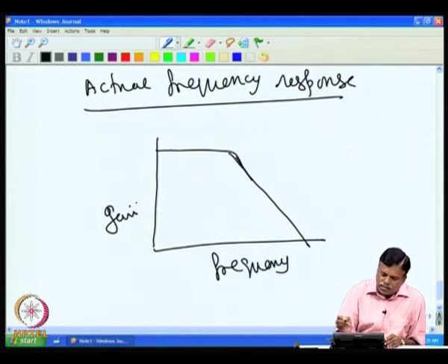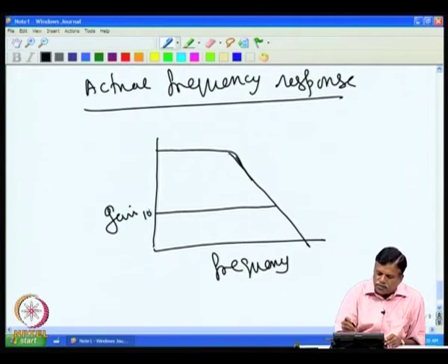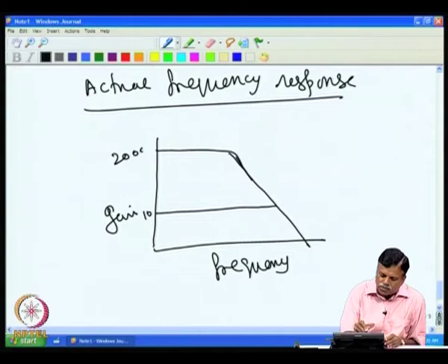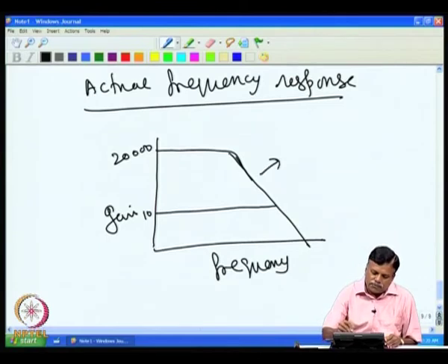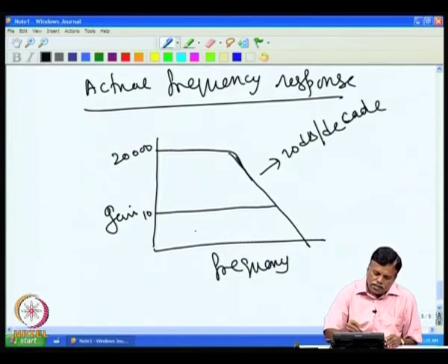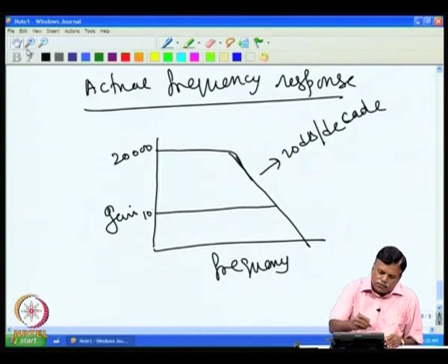Then if I set the gain, this is a closed loop gain. For example, if I want gain 10, the open loop DC gain is maybe actually 20,000. For example, for 741 the DC gain would be around 20,000 minimum, and then this is falling at the rate of 20 dB per decade, and the closed loop gain is 10 at low frequency.